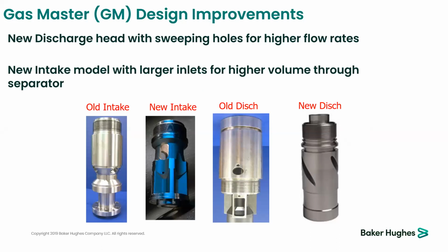Same for the old discharge. The old one has a narrow and straight discharge port, while the new one makes almost a 45-degree angle and is wide enough to make the flow homogeneous and not create a turbulence effect in that area.